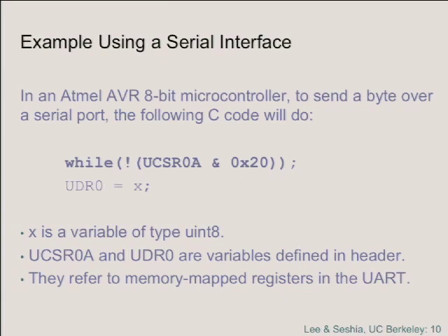It's gone. It's out over the serial port. Not really. It actually is at 58 kilobits per second. It's going to take a while to get out. That's why you need this while loop here. How long? Assume we've got basically 58 kilobits per second. That means that to send 8 bits is going to take 139 microseconds.